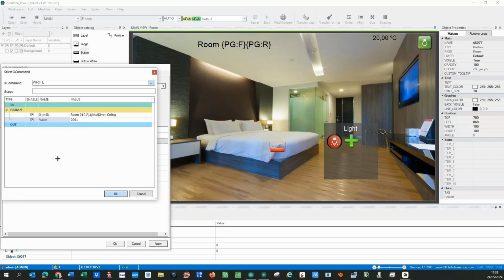This is in binary. Before it was plus 100%. So I wrote a 9 in decimal. Now it's decrease 100%. So I just have to put 1. But this is not 1 for turn on. It's 1 in 4-bit format. So it's a dimming, the 4-bit value is 1, so it's decreasing 100%.